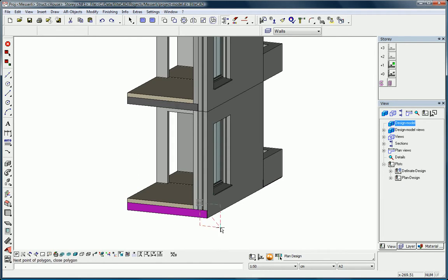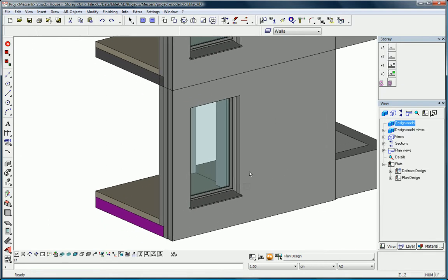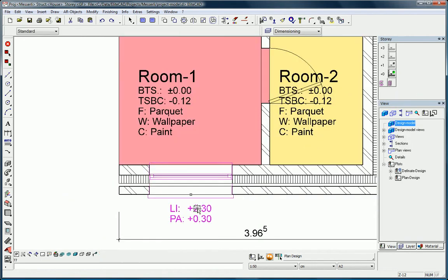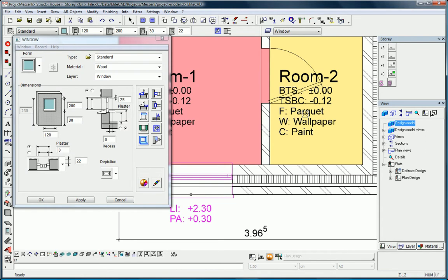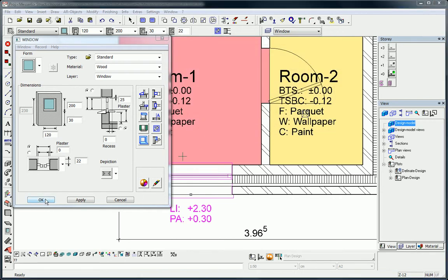The building component parametric is an elaborate function of EliteCAD. For example, we can apply this to a window of the model. Here, for example, we can go into the floor plan view, click on this window. Here we would like to make adjustments to the frame and the wing profiles so that they accord with the real windows. These components are then immediately adjusted to correspond.